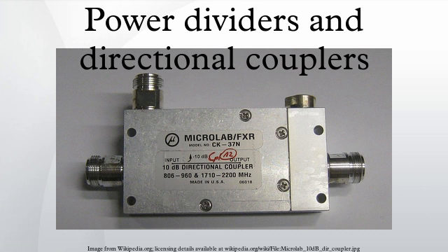Consequently, the isolation between the input and the isolated ports may be different from the isolation between the two output ports. For example, the isolation between ports 1 and 4 can be 30 decibels while the isolation between ports 2 and 3 can be a different value such as 25 decibels. Isolation can be estimated from the coupling plus return loss. The isolation should be as high as possible.